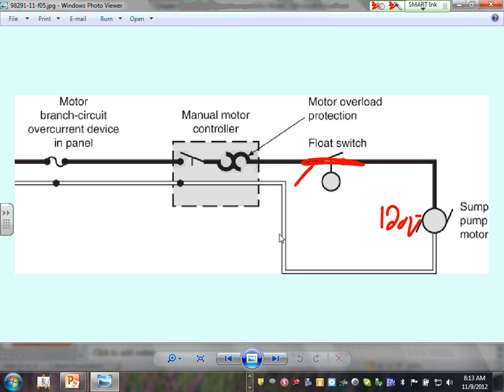If you graduate from your friend Dunway and you don't know how this control circuit works, you should ask your friend Chad for a refund. Really, do. So this fuse here will protect the conductors, the disconnect is required by code, the overload protects the pump from being overloaded, and then this one here is your controller that opens and closes. Cheapest, easiest way of control. This is typical for a lot of sump pumps. A dwelling is no different.